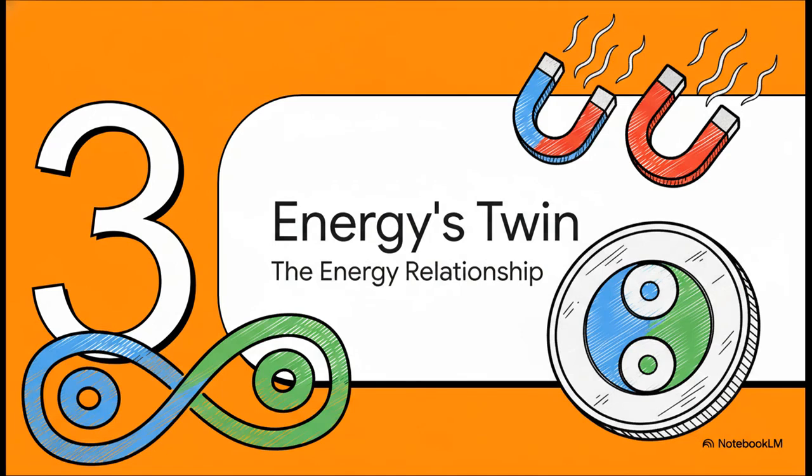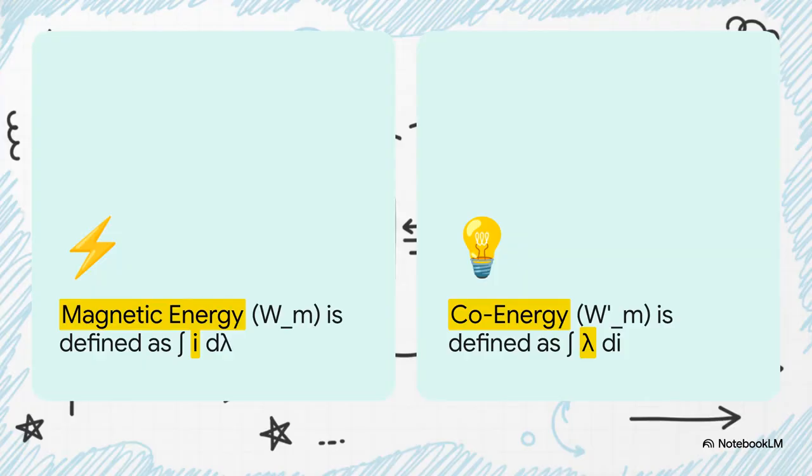Okay, so how does this magic tool actually work? Well, the easiest way to wrap your head around co-energy is to think of it as the complementary twin to the magnetic energy we're all a bit more familiar with. They're like two sides of the same coin, and their relationship is, well, it's beautifully simple. Just take a look at their mathematical definitions. You've got magnetic energy, which is the integral of current with respect to flux linkage. And flux linkage is just the total flux linked by a coil of wire. Then you have co-energy. And what is it? It's the integral of flux linkage with respect to current. They are perfect mirror images of each other. They just swap the roles of current, I, and flux linkage, lambda.